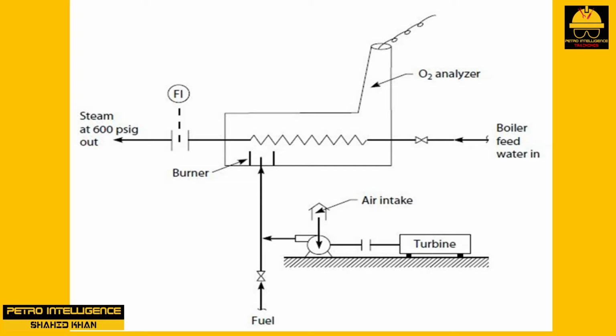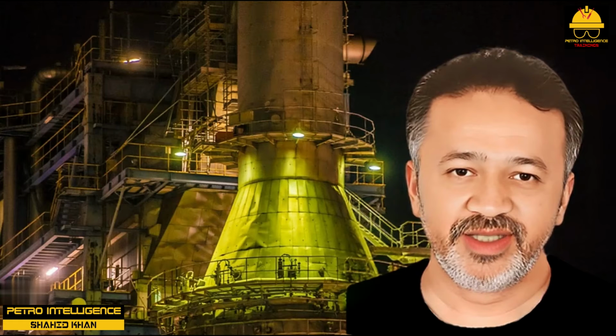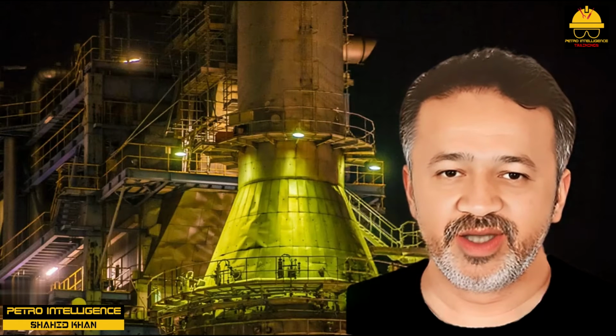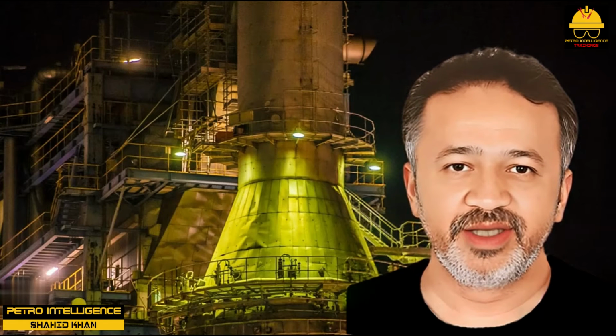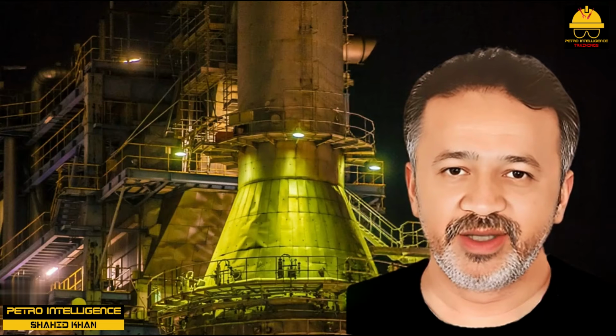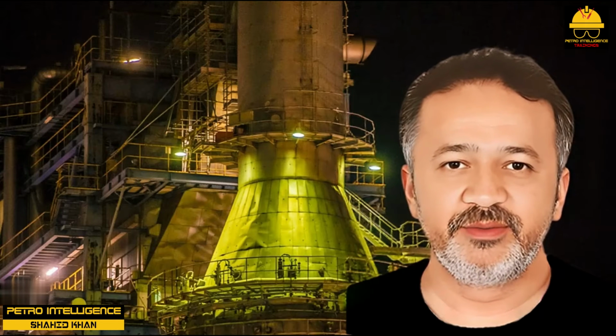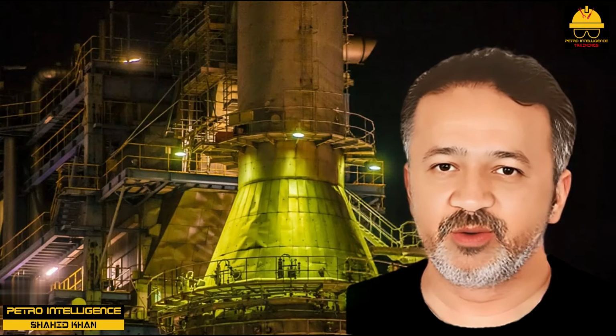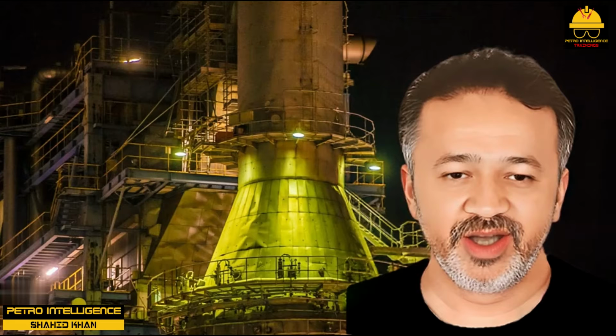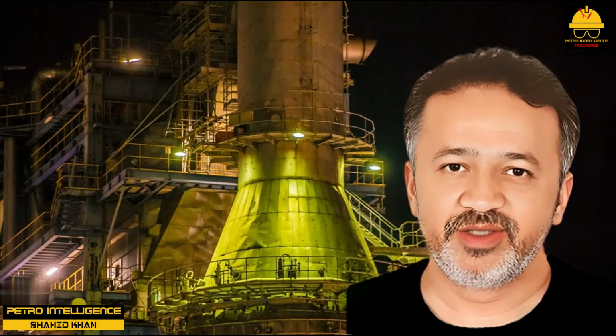It will not necessarily be a 2% O2 or any other fixed oxygen content. The oxygen content of the flue gas at the point of absolute combustion is a variable, depending on air-fuel mixing efficiency. The term absolute combustion is not the same as complete combustion. Complete combustion is a theoretical term, implying a theoretical goal that we might aim toward but will never quite reach on any real process heater or boiler.